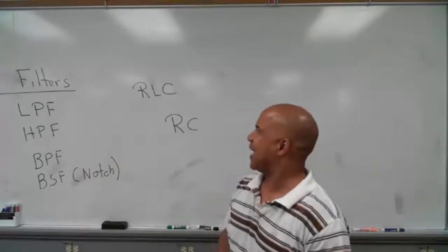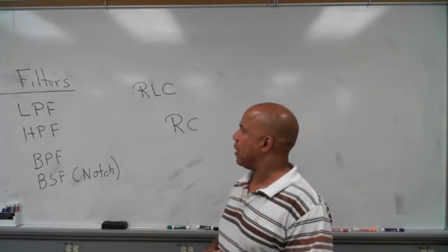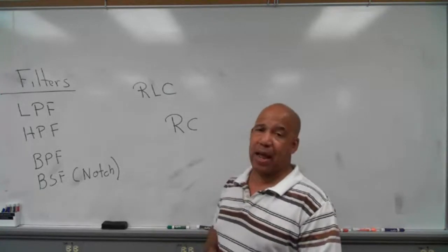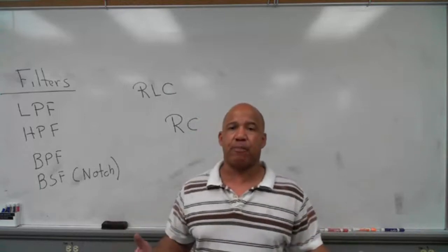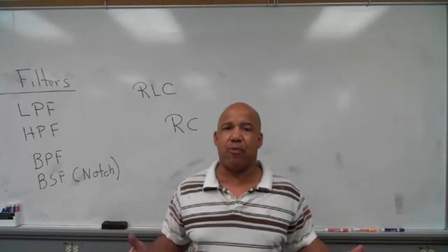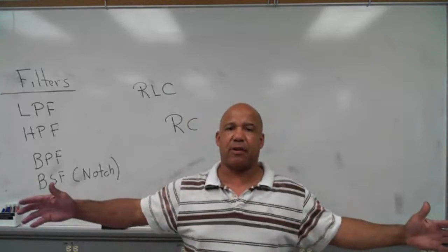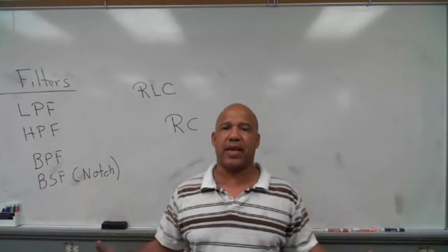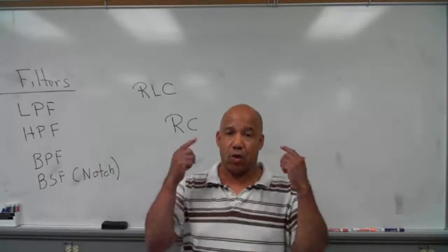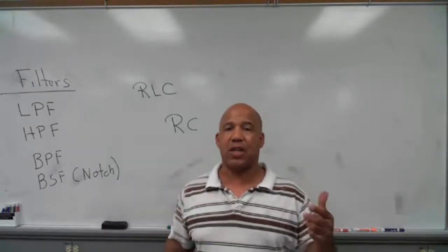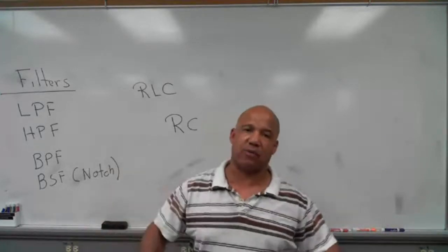And then we did kind of a high-level problem. We worked through an application. It was an audio application where we have this thing called a speaker, and the speaker has a certain bandwidth, and the bandwidth of the signals is way wider than one single speaker can handle. So we said, all right, maybe we can divide this bandwidth up into chunks, the bandwidth being human audio bandwidth. And instead of using one speaker, we'll use three speakers that have different bandwidths, one for the lows, one for the mids, one for the highs.